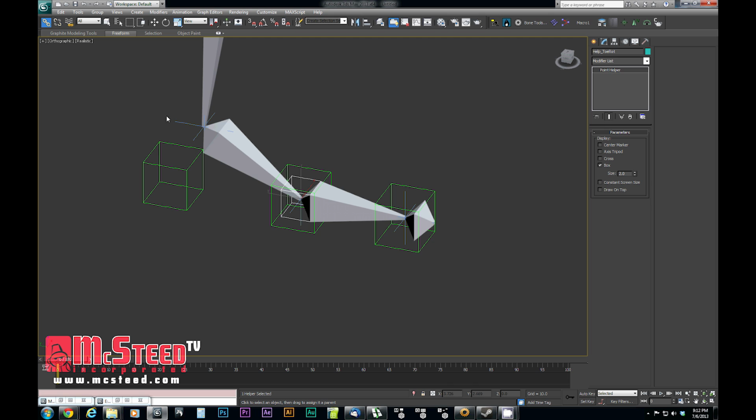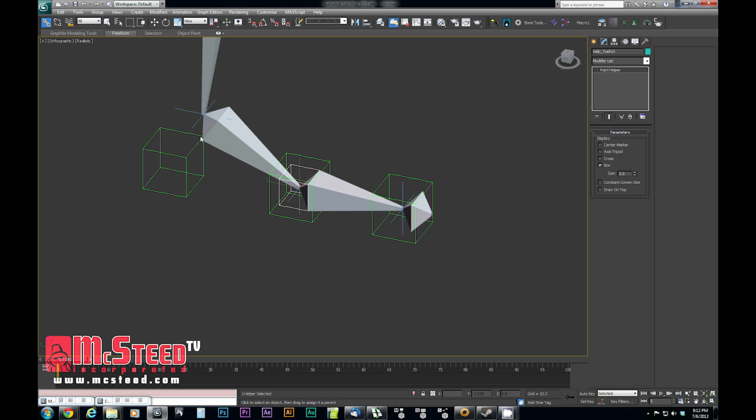So now I'm going to set up the hierarchy of how the different IK chains and the helpers are connected to each other so the foot can roll properly when the setup is final. Okay, so as I said before, this gets parented to that. This IK chain gets parented to the toe. And this IK at the end of the foot gets parented to this toe rot, the small helper in here. Notice that this guy is not named correctly.